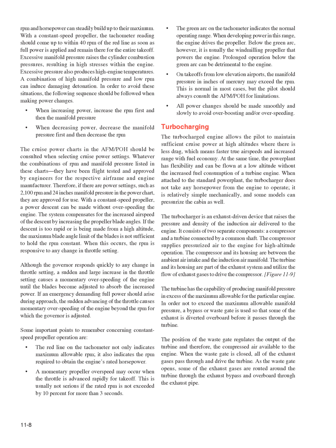On takeoffs from low elevation airports, the manifold pressure in inches of mercury may exceed the RPM. This is normal in most cases, but the pilot should always consult the AFM/POH for limitations. All power changes should be made smoothly and slowly to avoid overboosting and/or overspeeding.